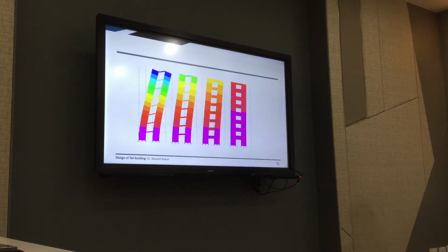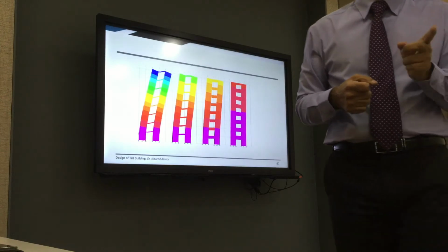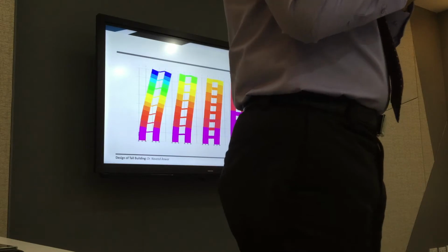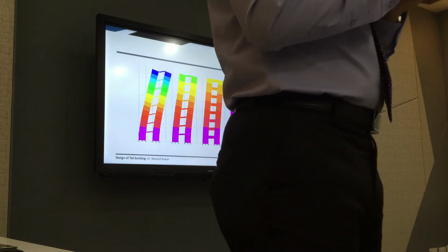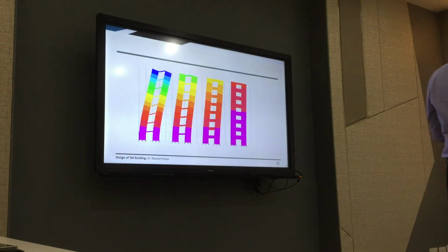I gave you the example of the previous class. What did they do? What did your previous class do to prove this point? I explained this to you. Unbreakable beam. They created an unbreakable beam in which they provided the flexural reinforcement in such a way that bending failure will occur before shear failure. So the beam could not be broken. It deflected a lot, but it never broke, because it can break only in shear. Bending can only cause deflections, not failure.